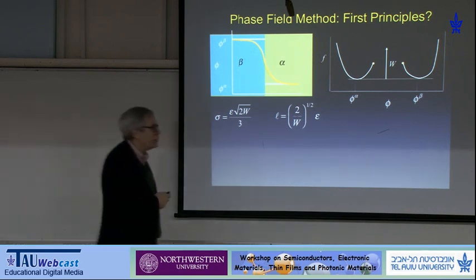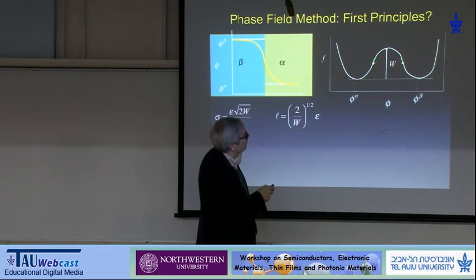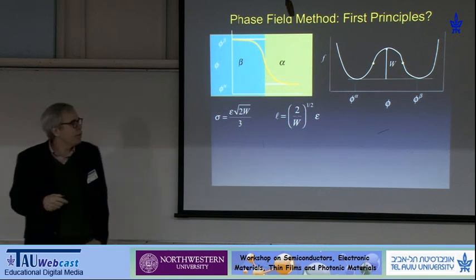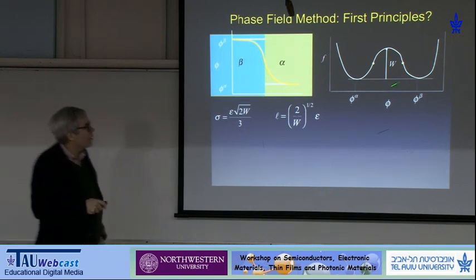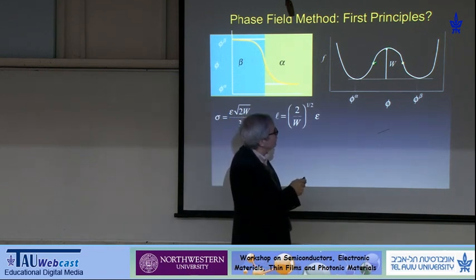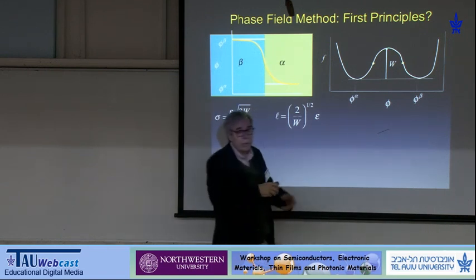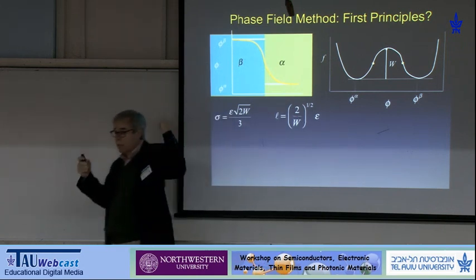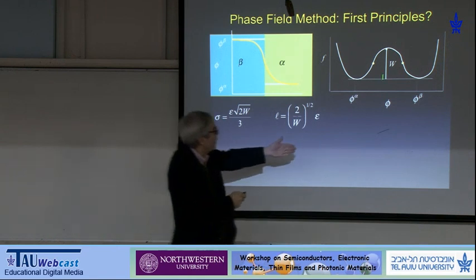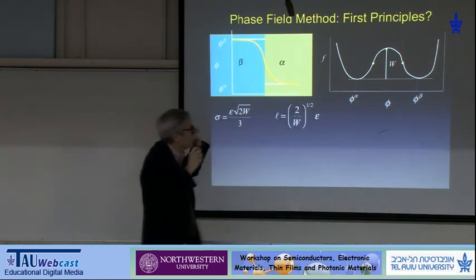And the problem is that this part of the free energy function is in the unstable region of the system. In other words, if I put a little bit of material of composition here in between these two spinodals, it will spinodally decompose. And that's what I showed you in those pictures, right? I quenched to 50%, and I end up with this beautiful spinodal structure.